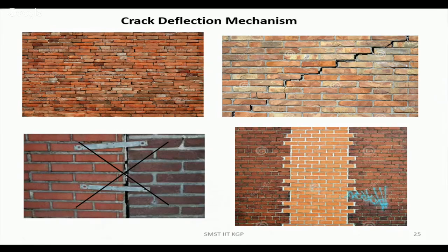We need a material with a highly interconnected porous structure into which bony tissue can grow, so that there is no sharp interface, but rather a zigzag interface, and a huge amount of material and bone interact with each other and load transfer is very gradual. There is no sharp load transfer, and that gives you toughening.